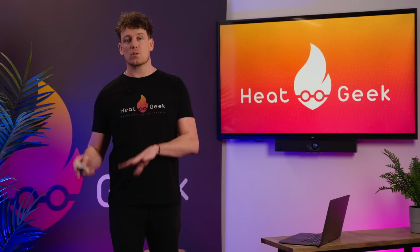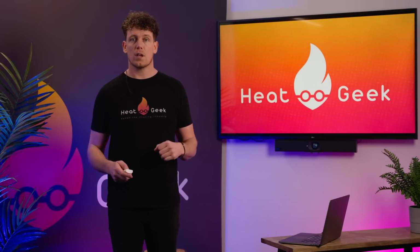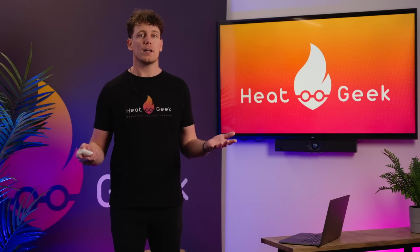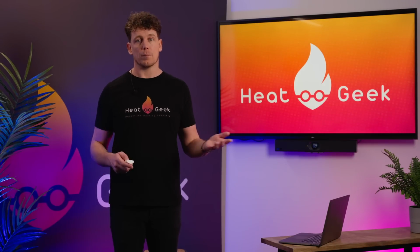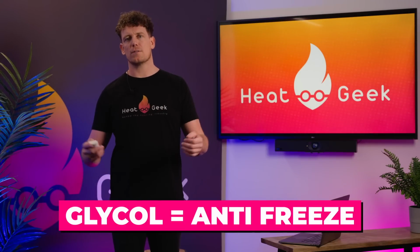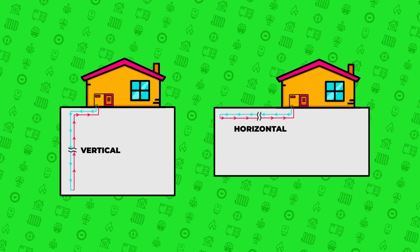Collectors are pipework that ground source heat pumps use to collect or deposit heat into the ground with a heat transfer fluid. Historically, this was made up of a mixture of water and salt called brine. The addition of salt lowers the freezing point to around -20 degrees C to enable the ground loop to run around 0 degrees without any risk of freezing and damaging the equipment. This is the reason a ground source heat pump collector is still called a brine loop and the circulating pump called the brine pump. These days we use a mixture of water and glycol mixed to a freezing point of approximately -15 degrees Celsius. There are two main different types of collector: vertical arrays and horizontal arrays.